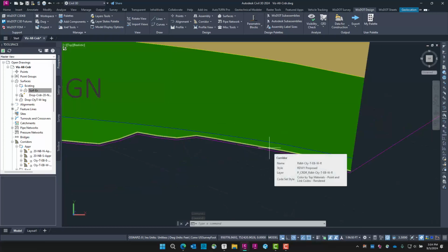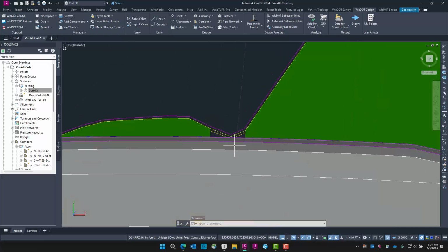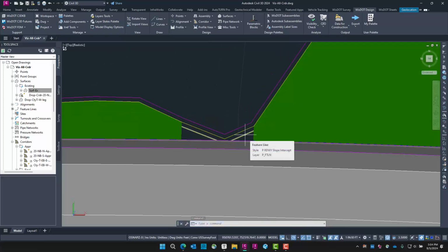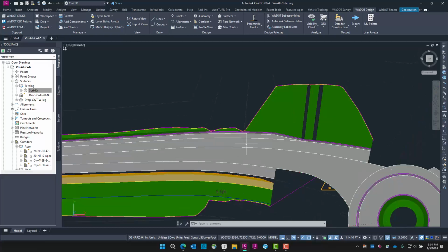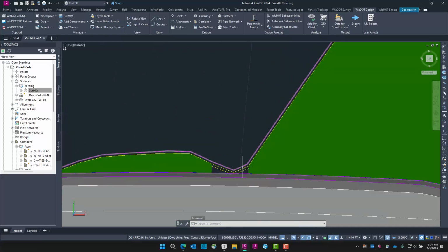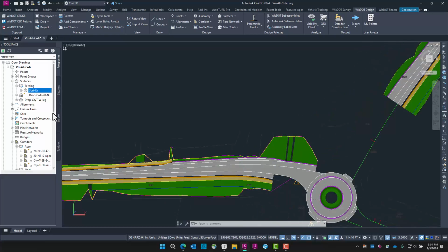created an automatic corridor feature line out of that. And then I did an offset here, like offset 1/2 foot in, down 10 feet. And then that made a surface, but then I had to wrap it right. So then it was offset, make it a 2D polyline, and create an outer clip or an outer boundary to tighten that up. I'm just going to add this other drop one to it, and I wanted to explain so that when we get to InfraWorks, you can judge whether it was worth that work or not.